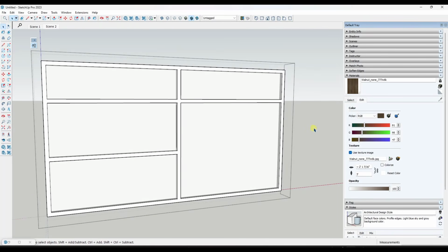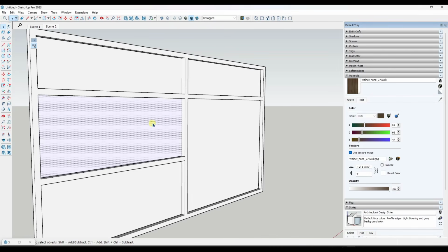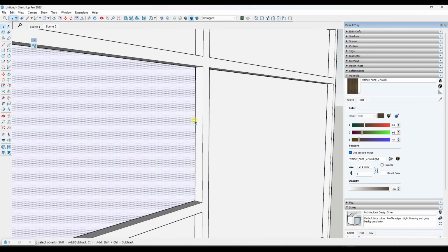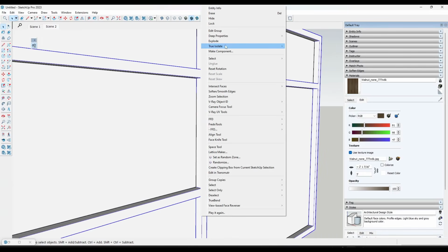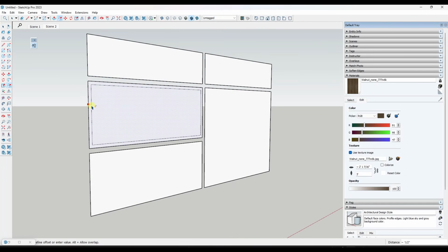So now all we need to do is come in here and create our cabinet doors, and we're going to do these in the shaker style again. So the first thing I'm going to do is right click and hide this surface, and I'm going to offset these in by whatever the gap is around the outside. So in this case, we might say 1/8 of an inch. And then you can mouse over more of these. So you can tap the F key. I'm going to do a Control T to deselect, but I can double click.